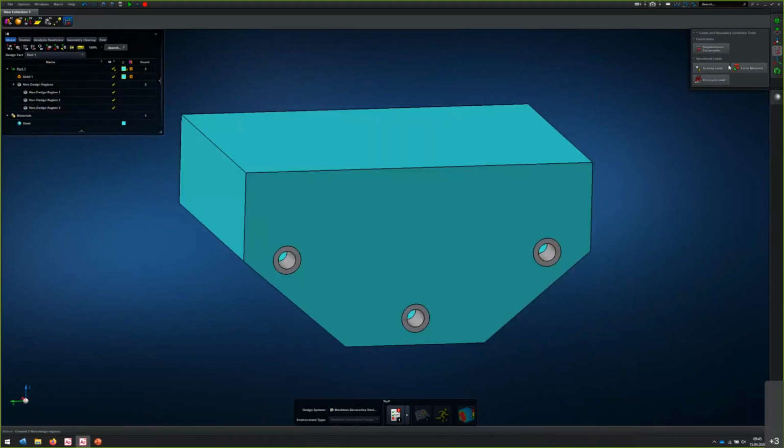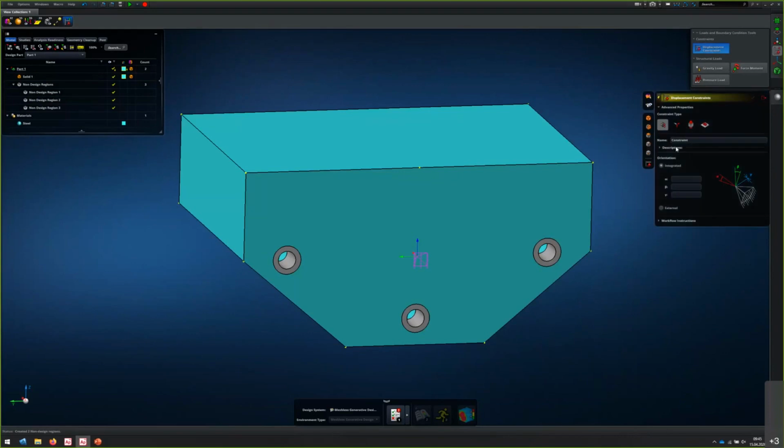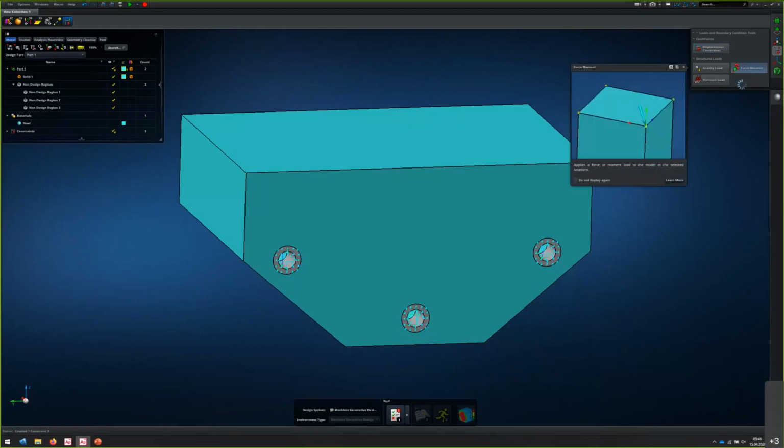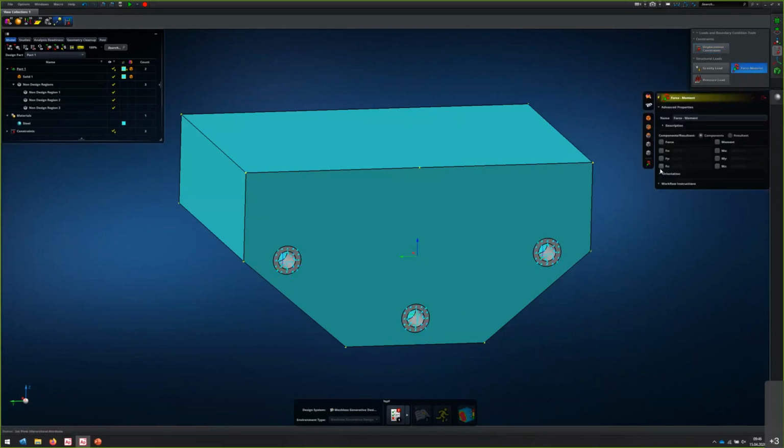We create our displacement constraints. For this, we are choosing the cells option because we want to use these just created non-design spaces as our displacement constraint. And we will fix all of them in all directions. Last but not least, we need our force, and we will put 1000 newtons in the negative Z direction and just put it on top of this bookshelf.